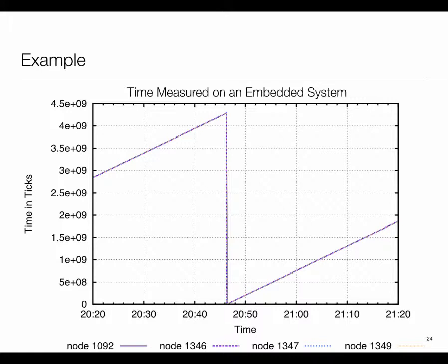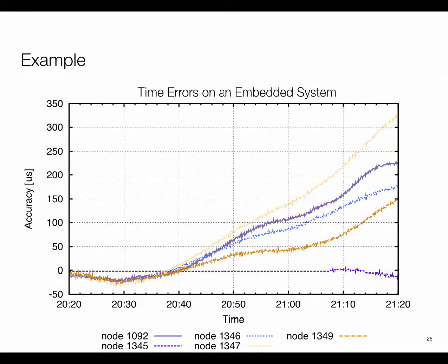So if you simply read these counters, you clearly see that there will be an overflow happening. The counter reaches its maximum value and then comes back down. And then again, just like the three-watch experiment, this is a bunch of wireless sensing nodes. Again, we start out with them synchronized, and we watch their evolution over time. In this case, we are watching the evolution of 4 nodes relative to 1 node, which we said was some sort of a reference.